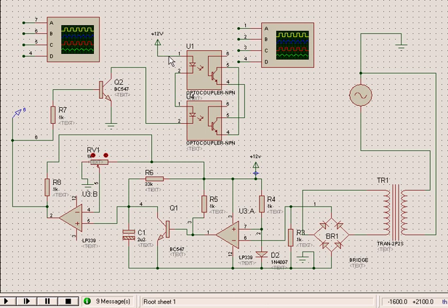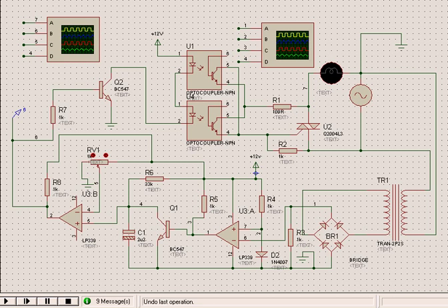And this connection is like this. That means this is connected to positive. Both of them are given in series. Actually in our case, in the MOC 3021, this point will go to the collector. But in this case, since we have to simulate this, we have used this fashion where the collector is connected to the emitter and the emitter is connected to the collector, so that current flow in both directions is possible, and that is how it has been made. Then we have to connect a triac. This is a triac, and then the load, which is a lamp, and then we will see how it works.